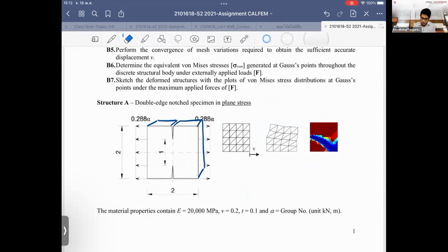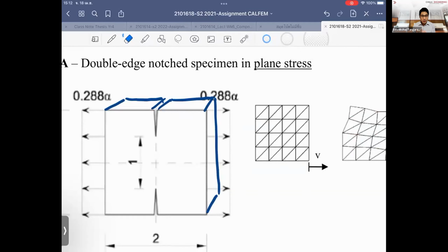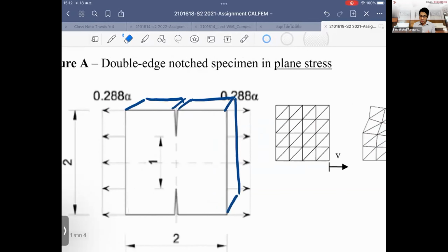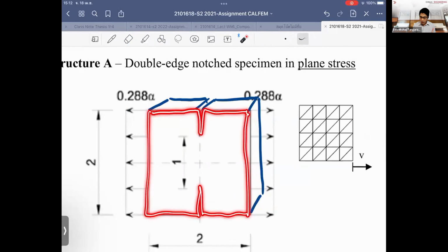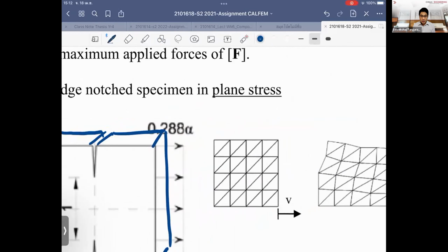When we say it's very thin, we're saying that the stress in the perpendicular direction is 0, because we allow the stress to transfer only within a plane. So it means we project the structure within the 2-dimensional plane. And in this plane, the stress in the direction perpendicular to the plane is equal to 0. That's why I'm saying that sigma, the stress in the z direction, which is perpendicular to the plane, is zero.